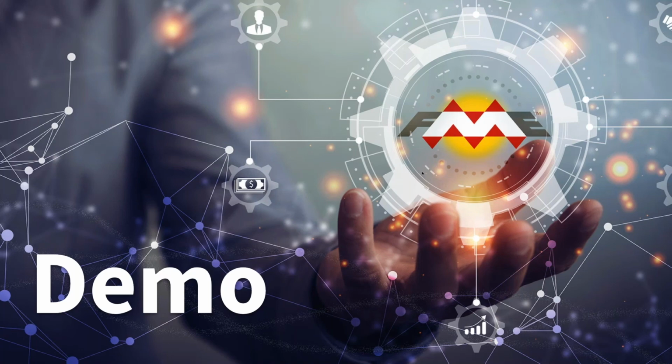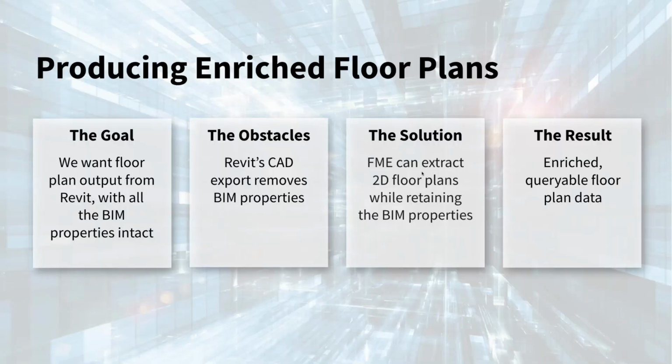I'm going to show how we can create an enriched floor plan from our Revit file. So we want to keep all of our BIM properties with our floor plan information. That's our goal. Now, Revit's native export to DWG for a floor plan does not include the BIM properties. So what FME can do here is we can read in just a 2D floor plan and keep those BIM properties so that we can produce enriched floor plan view.